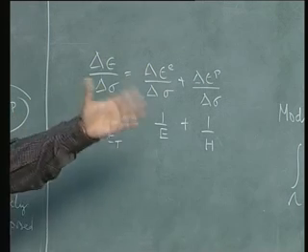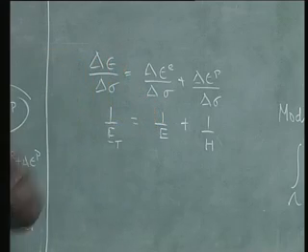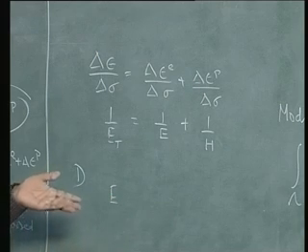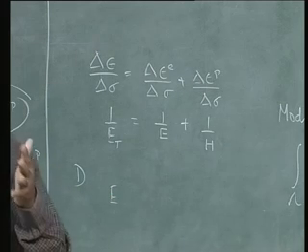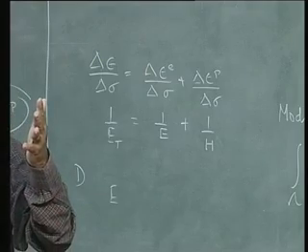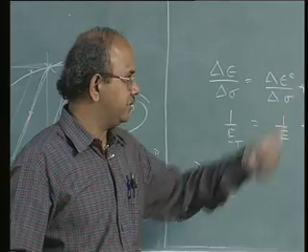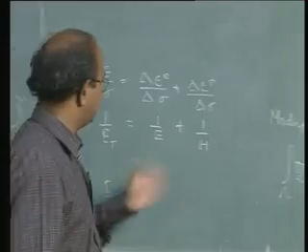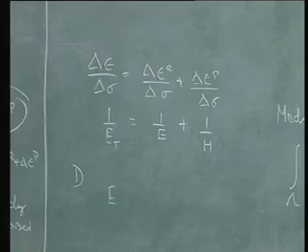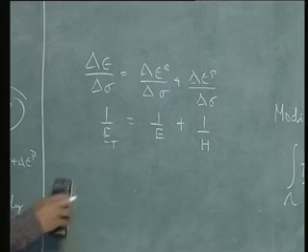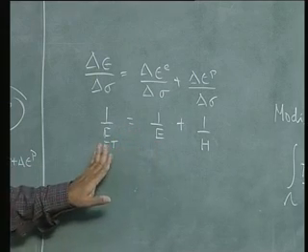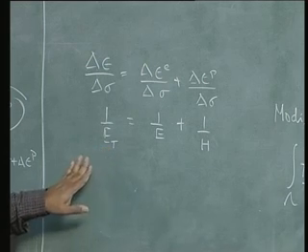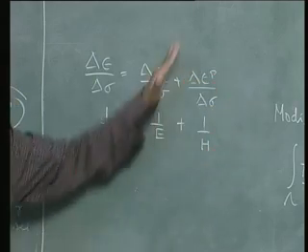It's a matrix. Actually, B is a matrix, Dt is a matrix. As a material, like you have the E matrix, D matrix, and you have the corresponding E to it. So E divided by 1 minus 2 nu into such and such, for example, you would have written. So that's what we mean by Dt, and the material property which enters into Dt is what I call Et. Note again one more important thing: unlike my good old friend E, Et may not be a constant. That's what we're going to see now, and this part also may not be a constant.